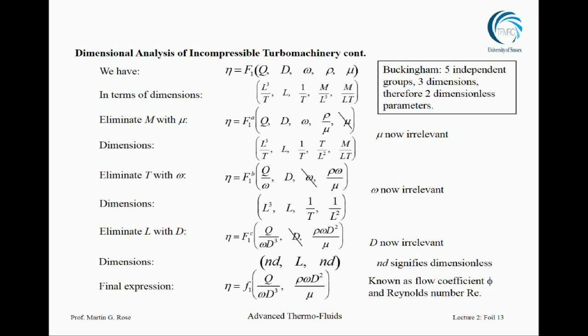If we get to a condition where only one term in the equation has a particular dimension, you know it's wrong. You know it cannot be there, because it's the only one with the singular dimension that's not present in any of the other terms. Once you get to that position, you can throw it away. And that is the logic which is used to reduce the number of dimensionless groups, by throwing out the ones which are left with the dimension in. Let me show you that happening.